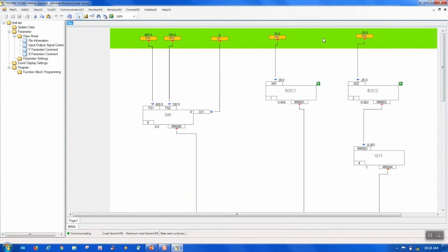But for this loop here, I've got 46, 48% because we're rising back up to our 400 degrees. And this is our output. It's going for almost 100%. We're getting closer to our set point, so we're backing off on that.